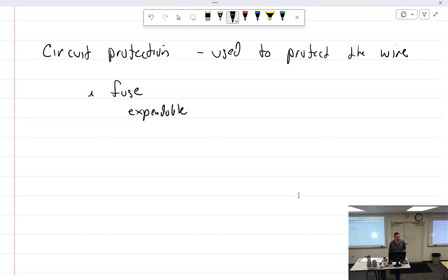So once they blow, you have to replace them. There's an FAR, oh, I can't remember what it is. If you have fuses in your aircraft, you have to carry spares. It's not 1 of every kind. I want to say it's like 2 of every single possibility you have. I can't remember the exact number. I want to say 5, but that could be more, the merrier. I don't remember offhand what the FAR is. So get rid of your fuses and put in a circuit breaker is the fun part.